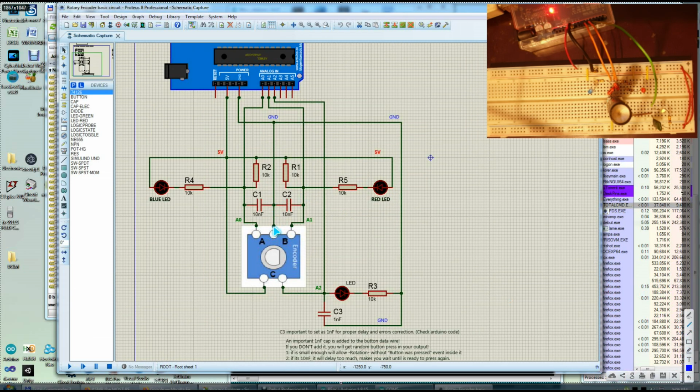So this is the negative line, what I'm having here from this middle point, you see, is going into this point, passing under that, this horizontal line is going under it and going there, like that. This is the negative line or the ground line, and is also here for this part as well. So this is the negative line, and this is the positive line, the 5 volts line, from that point into this bifurcation here, and from here to here, and is feeding directly this pin.